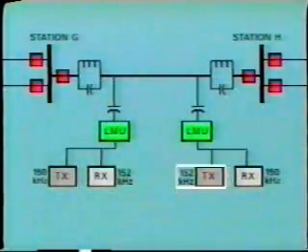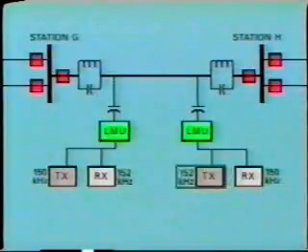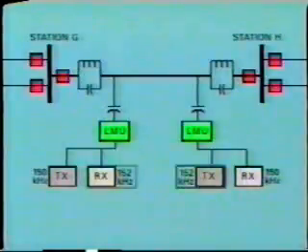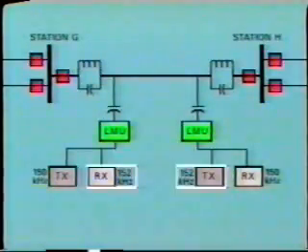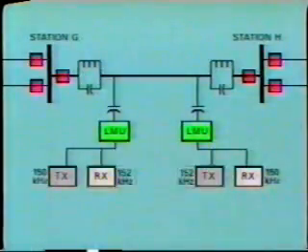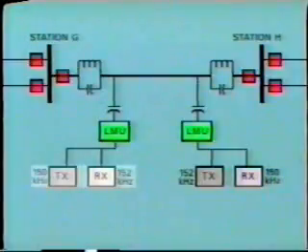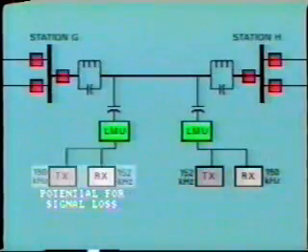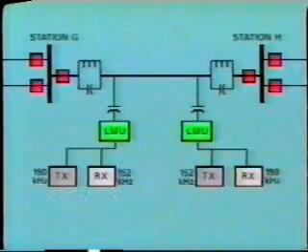In the other direction, the transmitter at station H is set to transmit at a mean frequency of 152 kilohertz. And similarly with the corresponding receiver at station G. The chosen frequencies are close enough together to use single-frequency line coupling equipment and line traps. But with this arrangement, there is the potential for significant signal loss and interference from transmitter to receiver at each end. But how come?